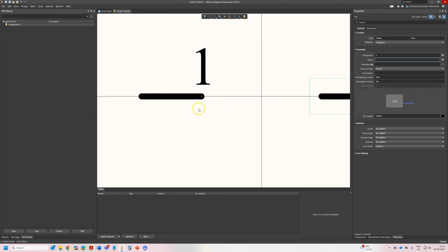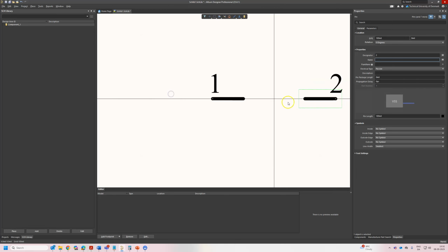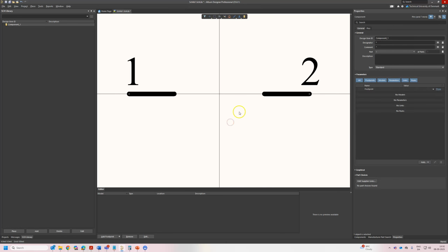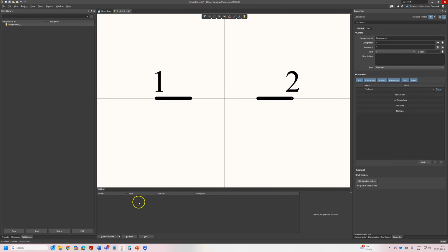So just a small note here where we have to connect our net. This should be faced the opposite way. So press the space. And now this is correct. Just note when you place your two terminals here, be sure it's set up to 100 mil, which should match your schematic.